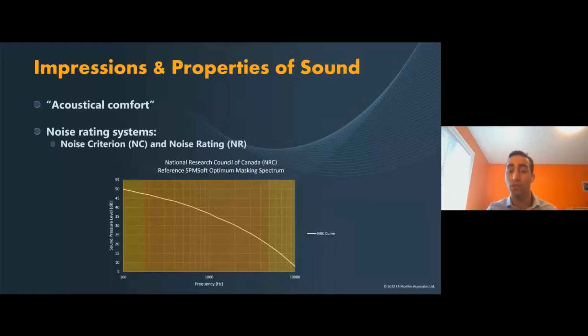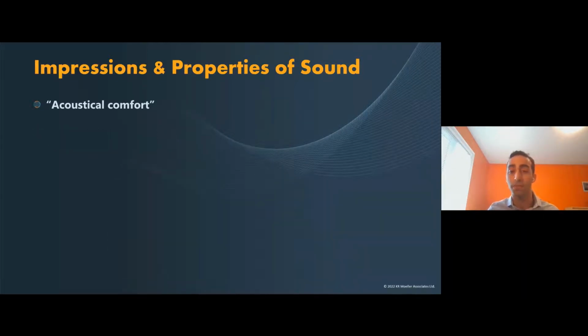For this reason, we've developed the A weighting scale, which is a set of correction values for frequencies that adjust for our sensitivities. We can use that scale to calculate the corresponding A-weighted overall sound level, dBA, to get a better sense of the annoyance that a particular sound would have on us. The data we're seeing on the chart here has an overall level of 56 dB, but a corresponding level of 48 dBA. It's important to not confuse the two.